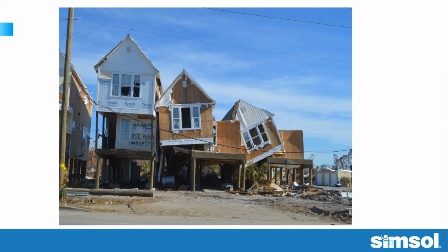Which I can tell you, after Michael, we saw a lot of them that didn't break away as such because the owners in previous years had made so-called improvements to strengthen those walls. And when they did finally give way from the flood, they took a lot of floor framing and issues upstairs with them as a result. That's an excellent point. Due to those altered designs and altered connections, when they stiffened those connections, when the failure did occur, rather than just the lower story wall breaking away like it's supposed to, it also tore out floor members upstairs, which caused subsequent collapses of the upper stories.